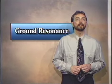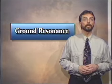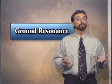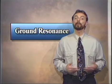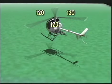Ground resonance is a condition in which the main rotor system becomes unbalanced, eventually leading to an uncontrollable pendulum-like oscillation of the aircraft. It's most likely to occur in helicopters equipped with a fully articulated rotor system. Normally the blades in a three-bladed, fully articulated system are spaced 120 degrees apart from one another and are constructed to allow some horizontal movement about the drag hinges. Remember, a fully articulated system must allow the blades to lead and lag to compensate for Coriolis force.